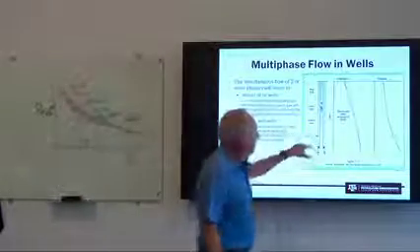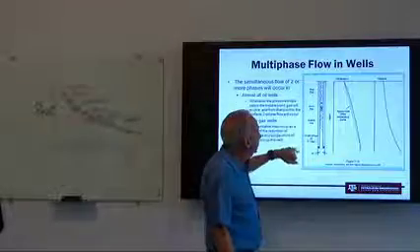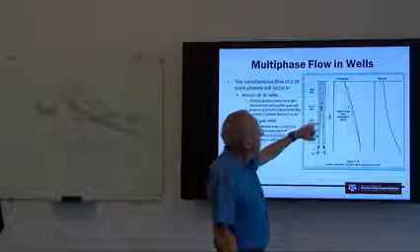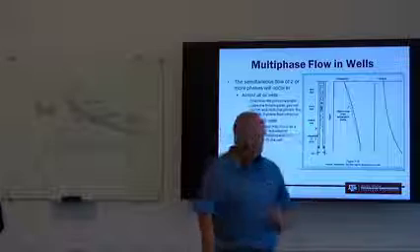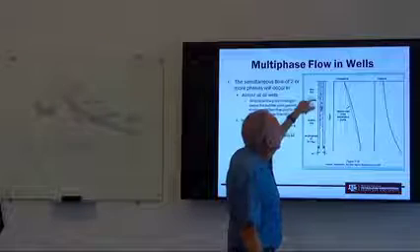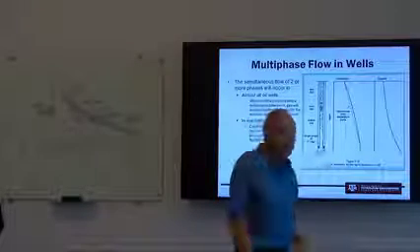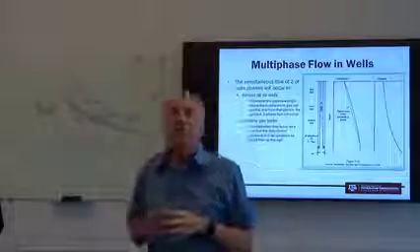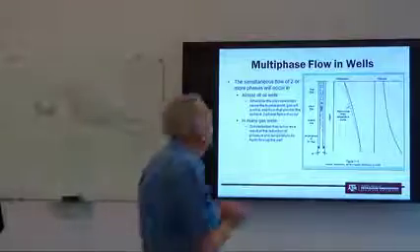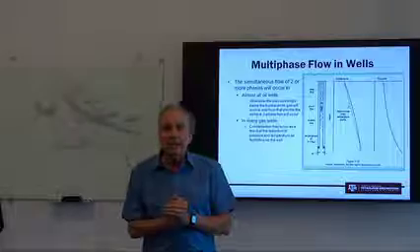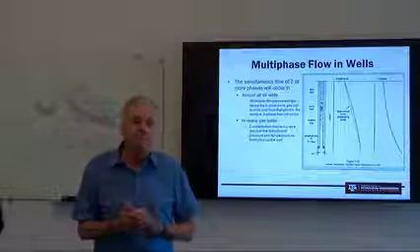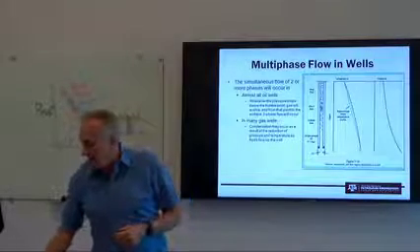very little gas. Here it talks about single phase liquid deep, we reach a point, the bubble point, where gas starts to come out of solution, and as it goes further up in the well, those conditions start to change, and we might get to, in this case it talks about slug flow, but we could have a significant gas flow at surface and very little gas flow deep down in the well. And that compressibility becomes a very important consideration as we try to design for optimized conditions in our wells today.